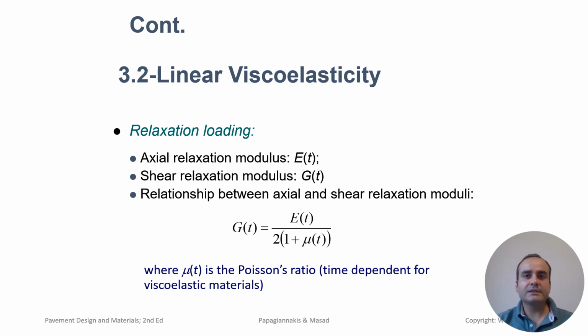The axial relaxation modulus and the shear relaxation modulus are both important measures of how viscoelastic materials, such as asphalt binders, respond to stress relaxation over time. These moduli provide insights into the material's ability to relieve stresses under different types of loading. The relationship between these two moduli is grounded in the material's mechanical properties, and their behaviors are interconnected to the theory of viscoelasticity and elasticity.